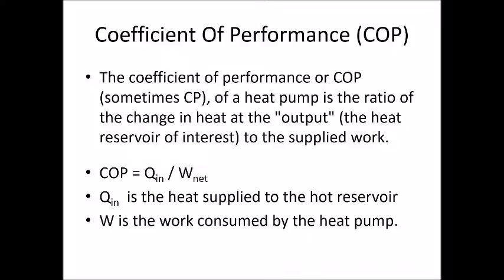So this is our sort of hybridized expression for efficiency, but we're not going to use efficiency for describing heat pumps and refrigerators, because it would be a complete misnomer. So in the industry, they say coefficient of performance, and quite often you'll just hear people talking about COP. You sometimes hear CP, but not really. It's mostly COP. So when refrigeration designers get together and they discuss who's got the best design, it will pretty much be driven on COP. There'll be a cooling effect as well, the temperatures they can reach, but it's COP that they obsess over.